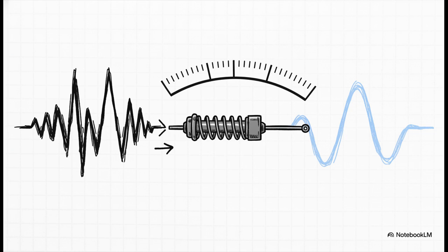But here is the real genius part. If the algorithm detects a frequency jump greater than 8%, which basically means the musician has actually turned the tuning peg or played a completely different string, the filter resets instantly, so it smooths out the noise but remains incredibly responsive at 60 frames per second when a real change occurs.